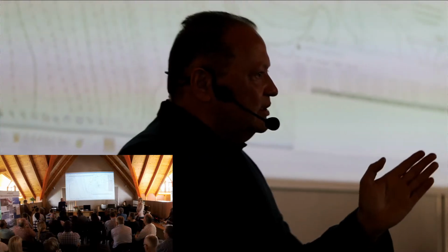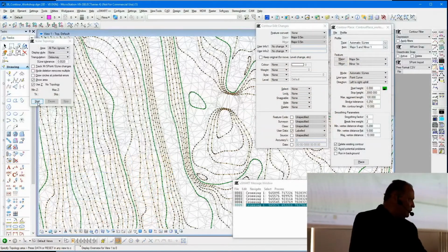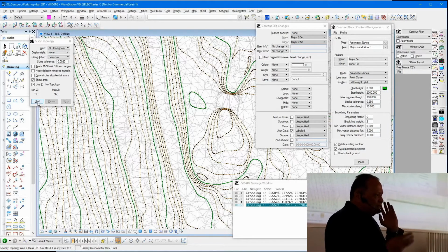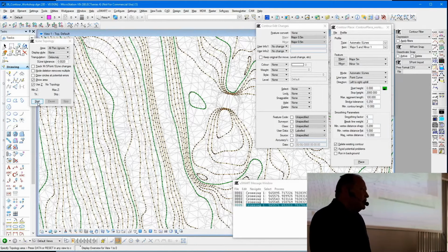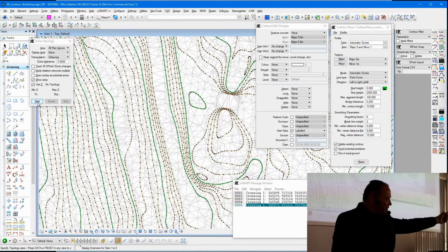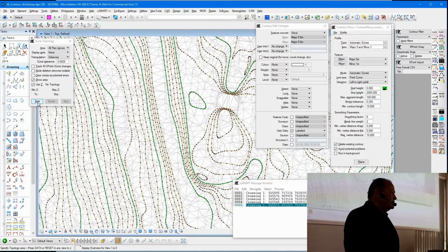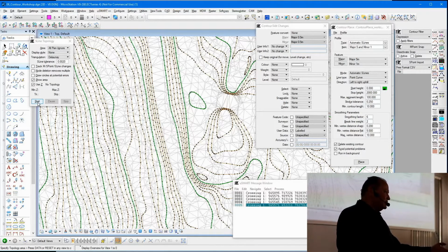But the point is that this is for everything for the future. So your road and everything, where you know now that the road must go through this point. I've got a point there on the ground, and now I missed it or whatever. So now I want to pull it, but there's a few other things because I drew it parallel to something else, and I want to move it. If you think along those lines, then for contours you might say, I've got a contour over there, 100, and another contour over here that's 102, and in between I've got a dead area. Typically, my XY position is halfway between these two contours.